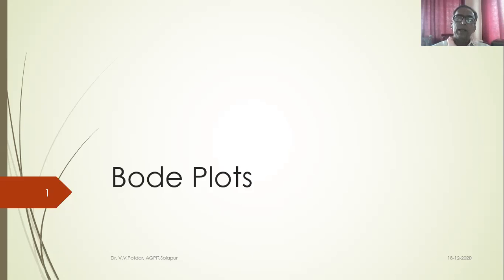Let us say it is climbing a slope, a ramp. So this suspension system is subjected to gradually increasing force. I call it a ramp function input. So this transfer function, which is the ratio of X(s) by F(s), I put F(s) equal to the input function, which is equivalent to a ramp function.